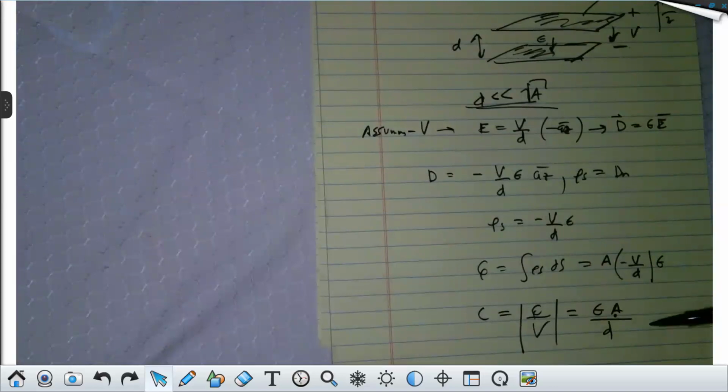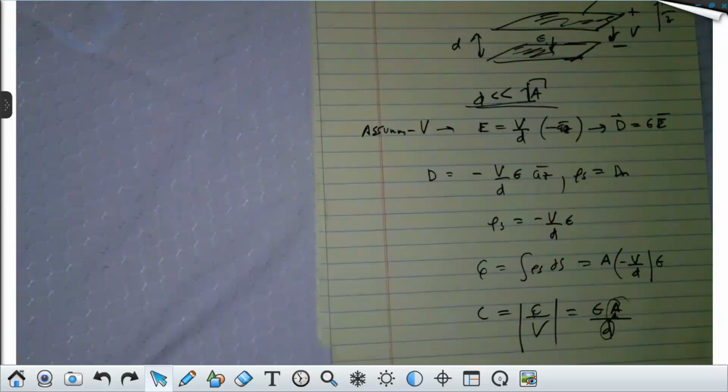And how many remember that formula for parallel plate capacitance? Capacitance is always proportional to plate area, inversely proportional to distance. Here's the trade-off. Remember I told you about people wanting supercapacitors? All right, here's the thing. As D gets smaller and smaller, the capacitance gets larger and larger, right? And you're occupying a smaller volume, by the way, aren't you? But look what happens to the E field. The E field is going to be whatever the voltage is divided by D. Well, as D gets smaller and smaller, the E field between the plates is getting larger, right?